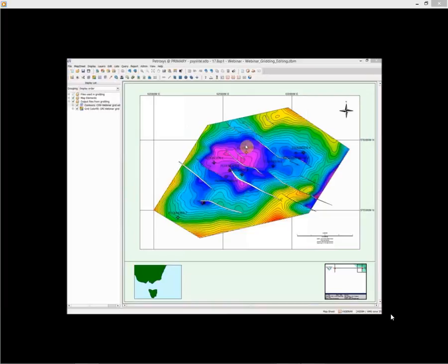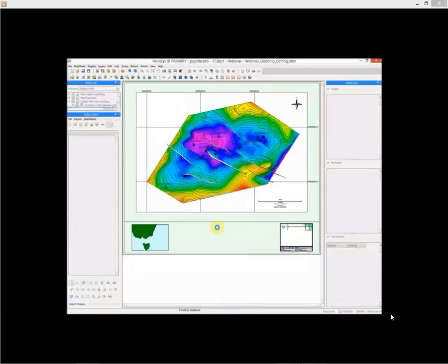Now, I'm reasonably happy with this grid, except for this region down here, where there are some spikes. The reason for this is the seismic around the fault is terrible, and as there's no way to improve it, I'm going to have to actually edit the data itself. So to do this, I'm going to take my grid into the new grid editor. Now, there are two ways that you can launch Grid Editor through the Spatial Editor. You can do this through the Edit menu and launch Spatial Editor, or I can right mouse button on my grid in the display list and open Edit. Now, as you can see, my grid has now been opened in the Spatial Editor.